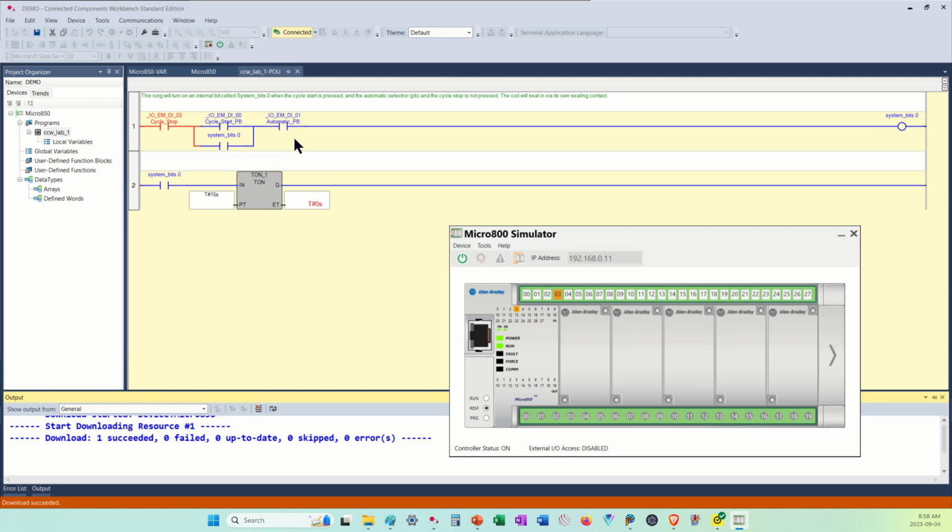And then I'm going to take my automatic, because it's a retentive switch. I push my automatic push button in, and now I've got these two. So I'm just going to toggle this really quickly off and on, and it set my system bit, it sealed itself in, and I de-energize it instantaneously, and now my timer, pardon me, is actually timing. And the actual value, my elapsed time, is being shown on the right-hand side, and the program value is on the left-hand side.